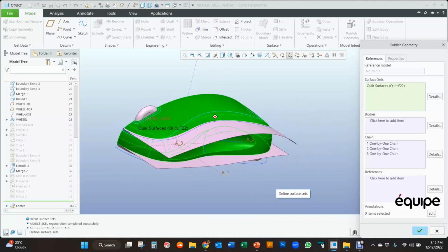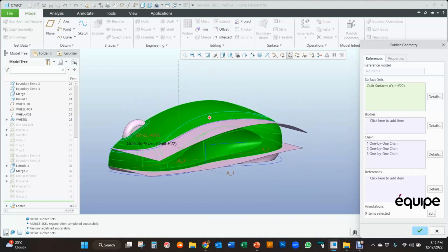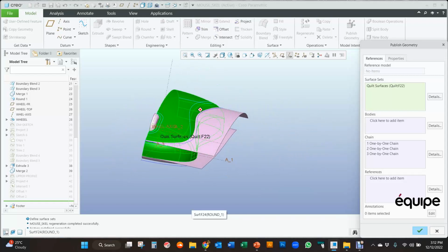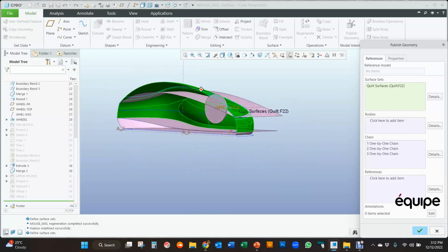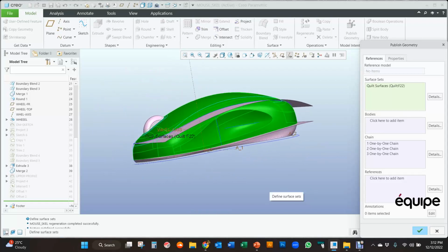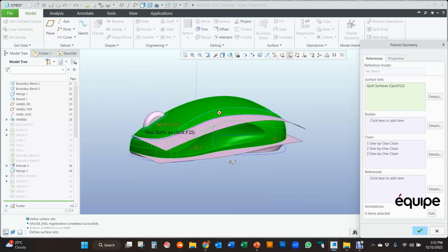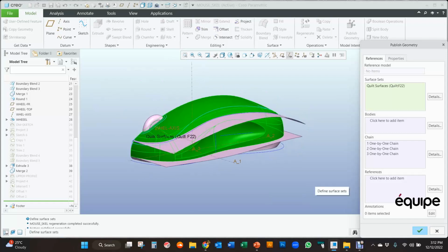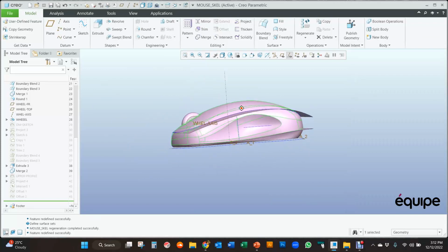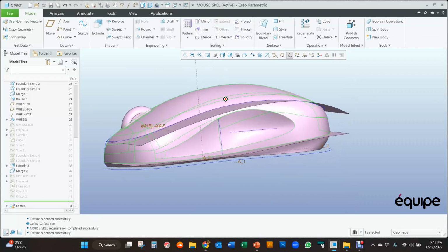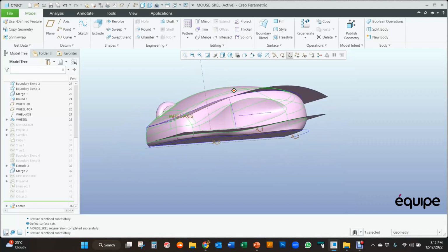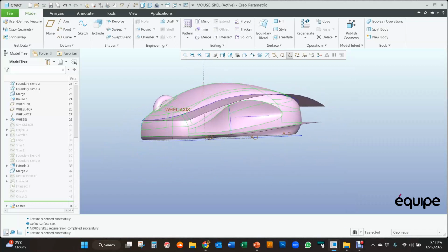So one fantastic benefit of Creo with published geometries is we're just selecting those geometries and features that are going to relate to that part, to keep that part as lightweight as possible. It also makes it very clear when you look at a new part, or someone else's part, which references from which skeleton geometries are driving those parts.